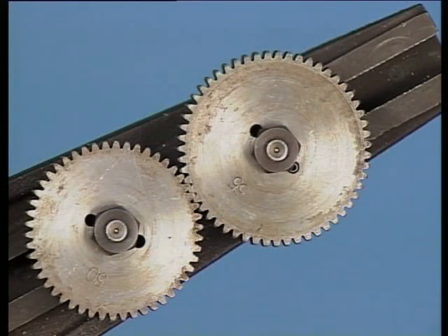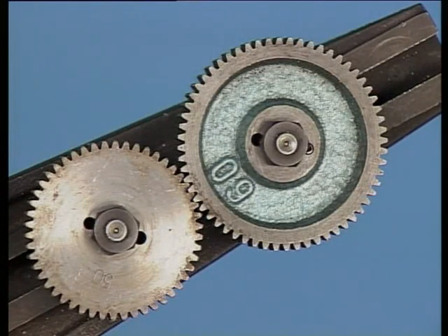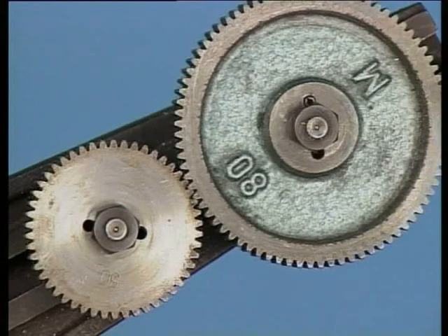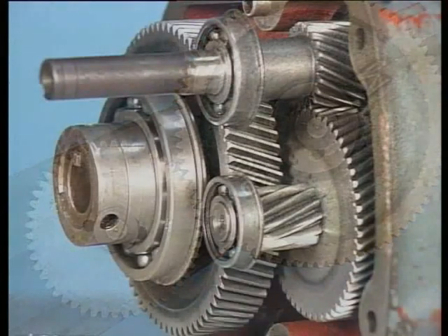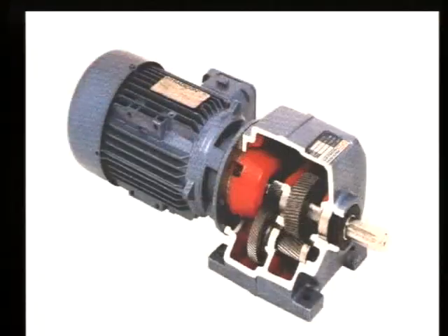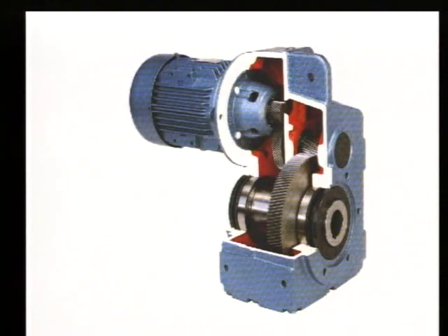So far, we have seen that by altering the ratio between the number of teeth of a driver gear and that of a driven gear, we can achieve a speed reduction. The process has involved only 2 mating gears. We call this a single-stage reduction, or simply a single reduction. Far higher reductions can be achieved by using sets of gears in a number of stages. After the break, we'll look at various reduction methods and reducer types.